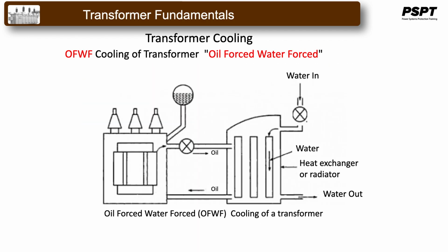We know that the ambient temperature of water is much less than atmospheric air in the same weather conditions, so water may be used as a better heat exchanger medium than air. And that is especially true if there is plenty of water available, which is the case for hydraulic generating stations. So quite often in some of the larger hydraulic generating stations, transformers, as well as some of the generators, have water-cooled radiators that dissipate the temperature away from the equipment.